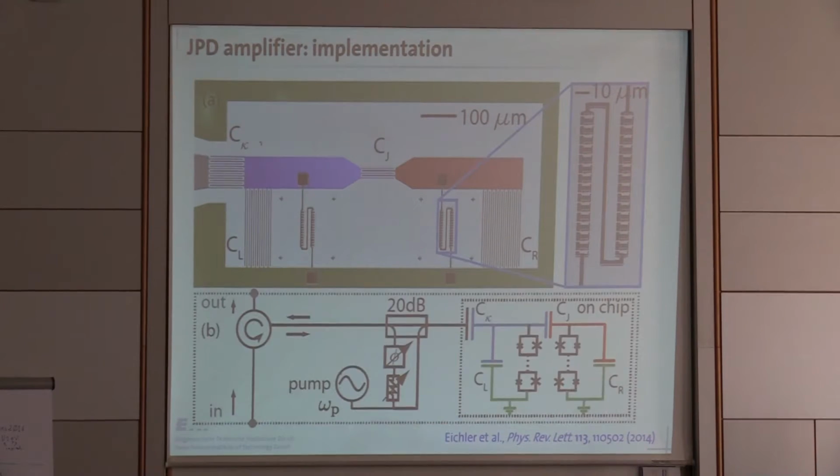So here are our parametric amplifiers, and maybe I should also say that every experiment in our lab that has a semiconductor amplifier now also has a superconducting parametric amplifier, because it improves the noise properties by somewhere between a factor of 10 and 100, and so all your experiments speed up by at least that factor. If you do microwave frequency measurements, you should be using superconducting parametric amplifiers. We've actually started to give them away to people who are interested. So if you're interested in using one of these, you could get in touch with us and see whether they are helpful for you.